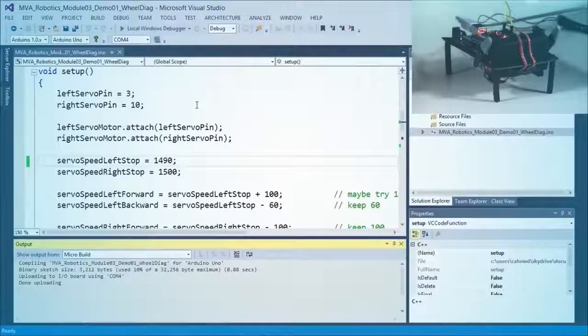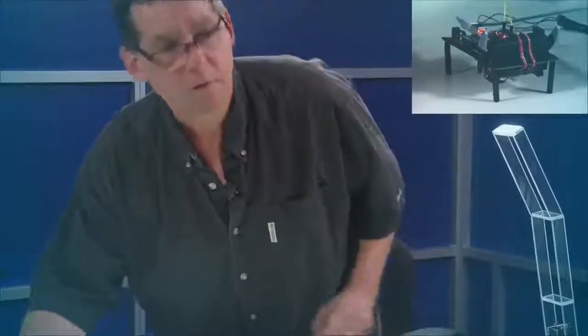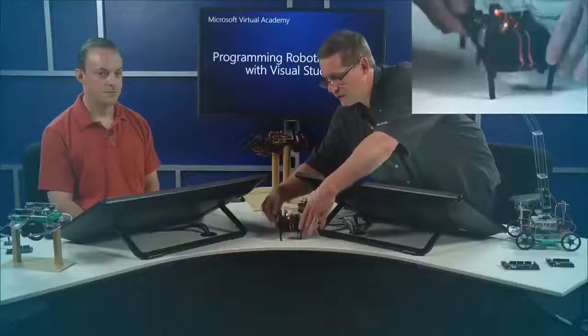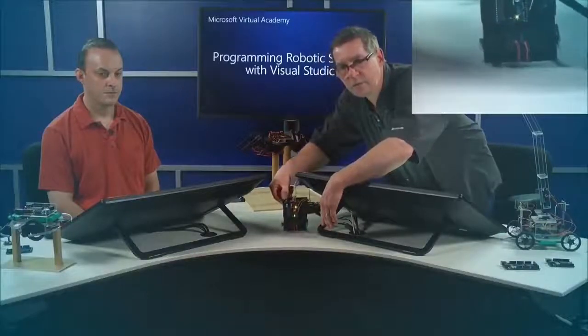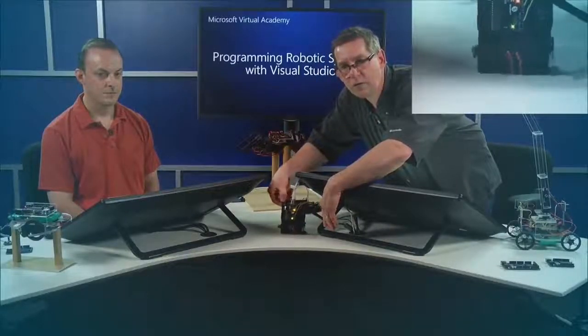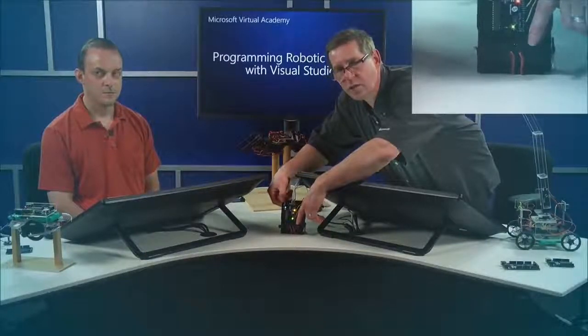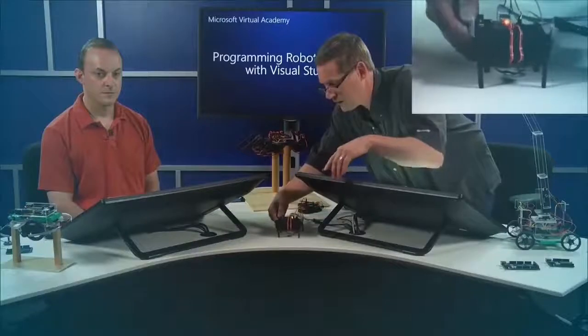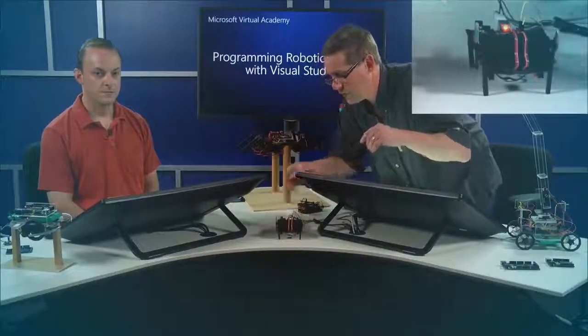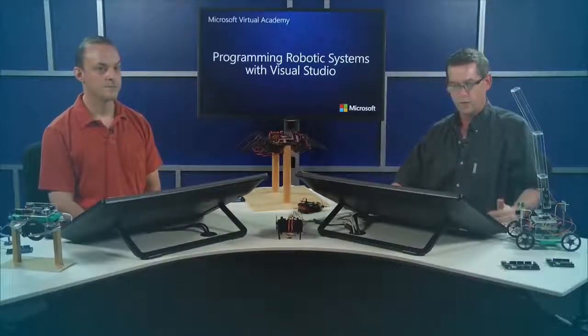So anyways, that's the idea of what you do. You adjust that. We could adjust it in hardware. We talked about this before. These servo motors have a little spot on them. I'm going to tip it up towards the camera, and you'll see the little areas. Do we have a good enough view to see those two little holes? Maybe not. But there's a little hole right here. There's a screw in there. There's a potentiometer, and you can adjust your zero position. That's good enough. So one of them seems to have stopped. We adjusted that correctly. You use the same technique for the other one.